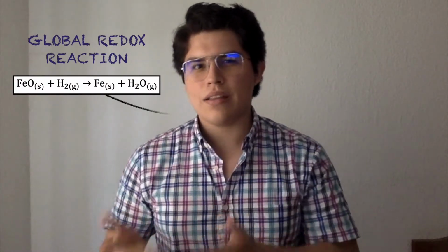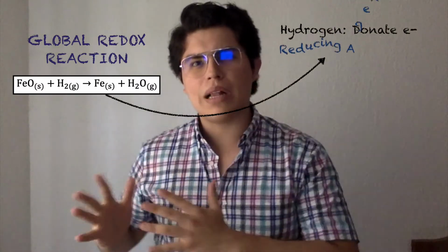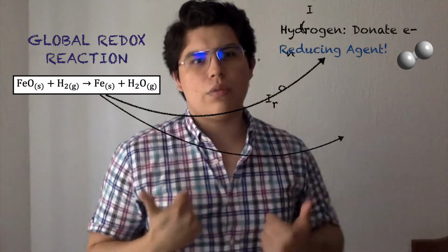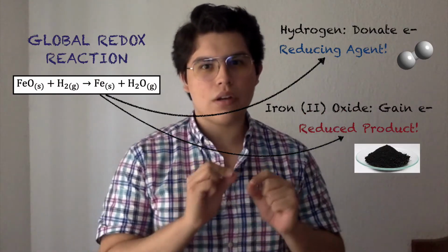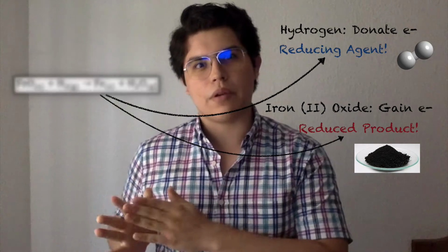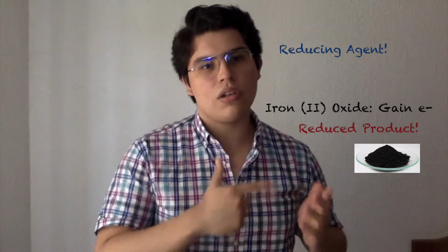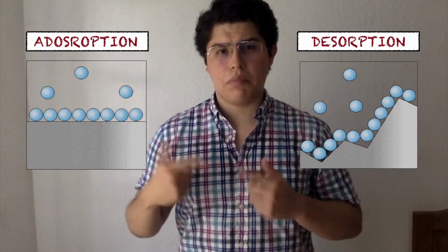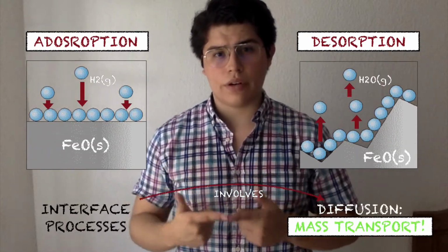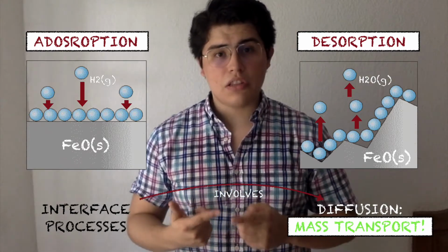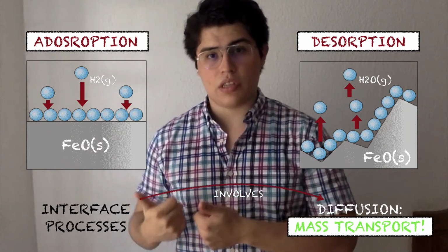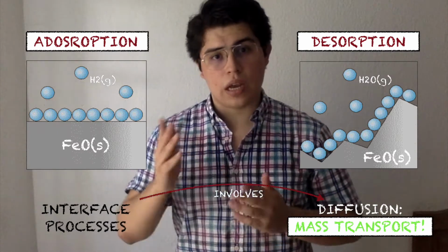As you can see, the role of hydrogen gas must be relevant for the limiting reaction step in the redox mechanisms, due to the capacity to convert all the iron oxide into direct reduced iron, which is the material also called DRI. This little equation suggests that both reagents and products find each other in different phases. That means that the limiting step for this reaction can also be limited by the mass transfer properties involved in the iron/iron oxide interface in this reaction.